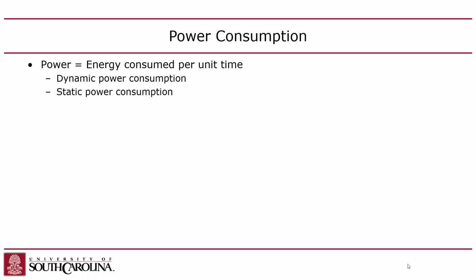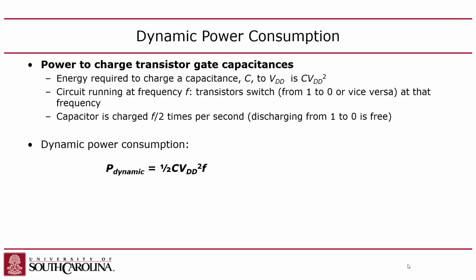So you can disable part of your chip by stopping switching, right? That will stop it from using dynamic power, but it's still going to use static power unless you can power gate and actually shut the power supply off to that part of it. The only way to get rid of static is to power down the chip or part of the chip, right?